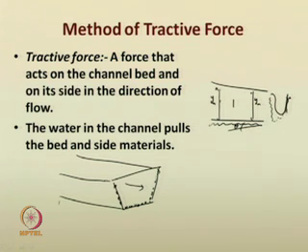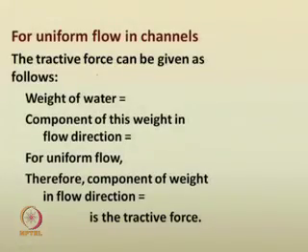As we had studied earlier, you can consider this entire portion as a control volume, and the weight of water enclosed by that volume acts vertically downwards. You can call it W if you wish. Based on that weight, the component of the weight will try to remove the particles on the bottom of the bed as well as on the sides of the channel. That is the quantity you have to determine: how much is the tractive force. So, as we mentioned, the weight of water, again for your convenience, I am just drawing it.